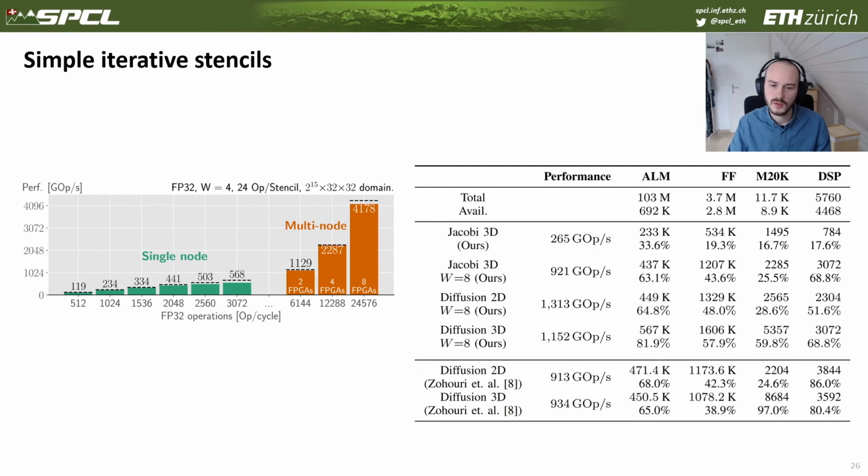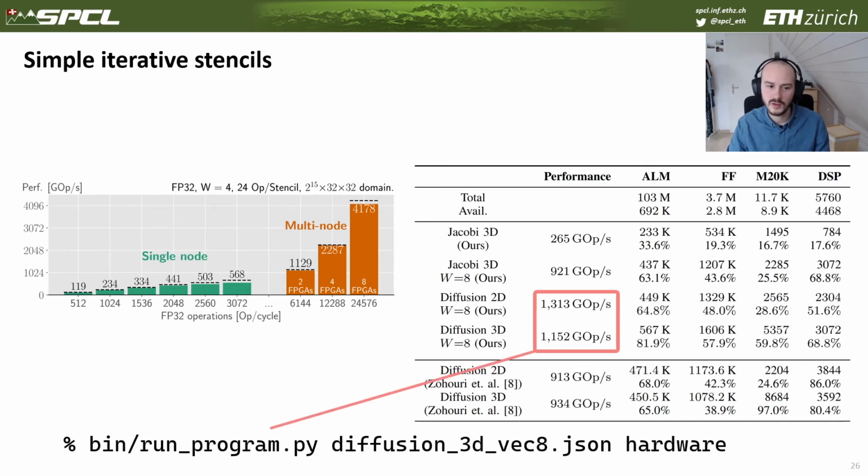What we show is that StencilFlow, from this fully code-generated code that starts from a high-level input, can be on par with or even outperform the hand-tuned codes, pushing 1 teraflop per second here for single precision, and in particular doing this with a fully automated stack starting from a Python front end, assuming you have the patience to wait 12 hours for the FPGA architecture to compile, because that is still the state of FPGAs today.